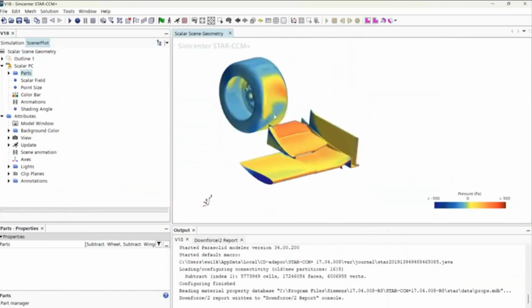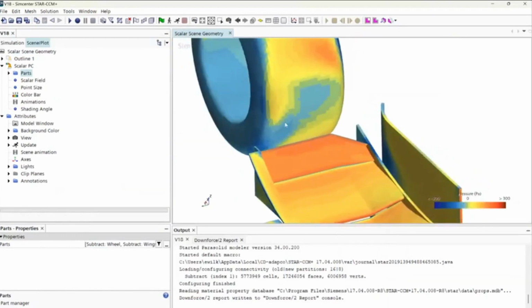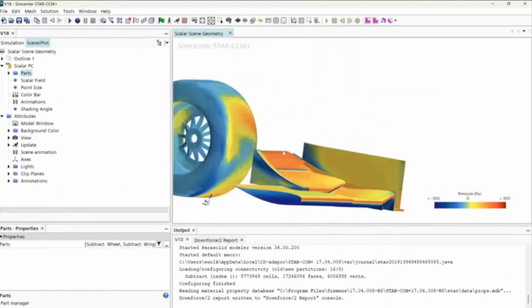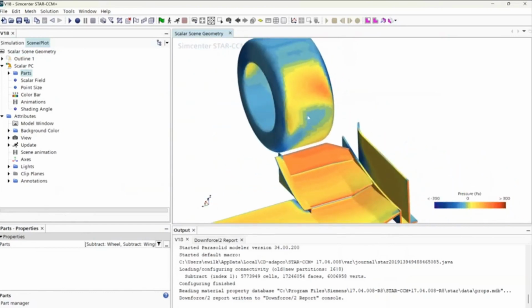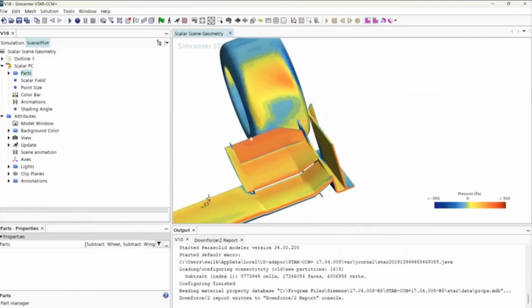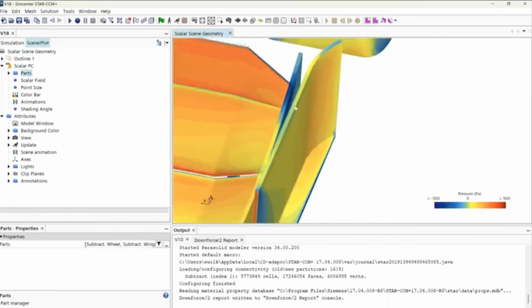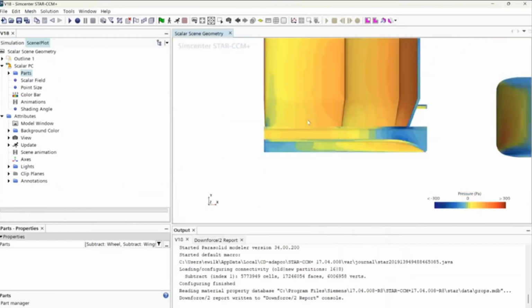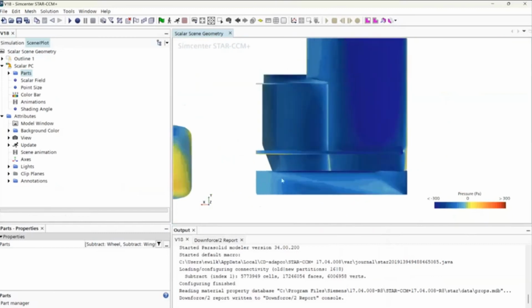You can also look at the tire and see there's a low pressure system here. The wing is creating low pressure right here, which is realistically decreasing drag by creating all this low pressure on the tire. With the outwash, you're getting this outwashing profile. You can just look at everything here. And of course, what you can also do is take two designs, put them like this, and realize what area is losing or gaining downforce, which is very cool.